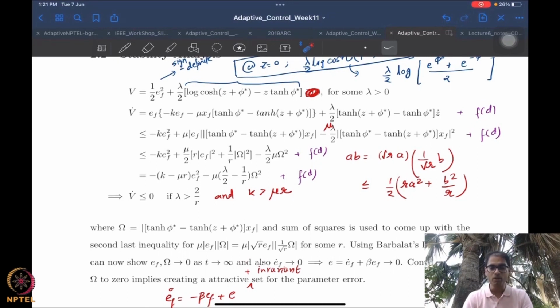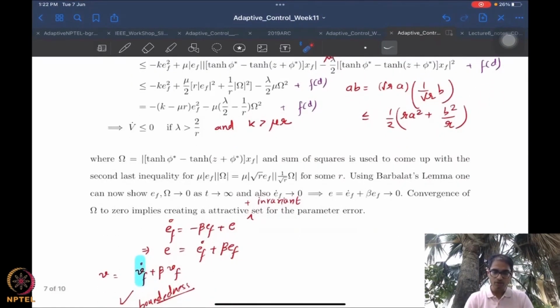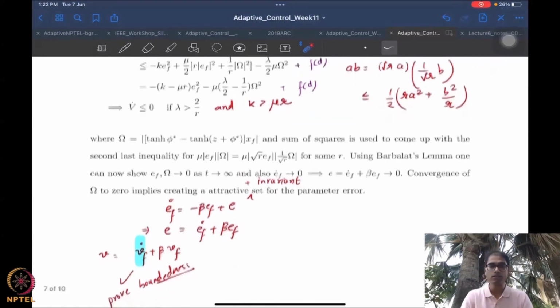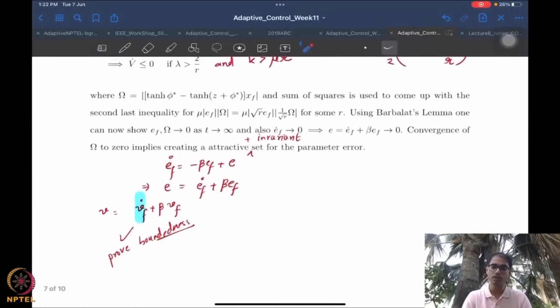And of course my parameters remain bounded, so my control remains bounded. My control will never become unbounded. It's irrelevant what happens, the control is never going to become unbounded, neither is the parameter estimate. So the disturbance may affect the residual set: instead of going to zero errors, you may not go to zero errors, but you'll get a residual set as you expect. You don't change anything in your parameter boundedness nor in your control boundedness. All right, that is the important thing to remember.